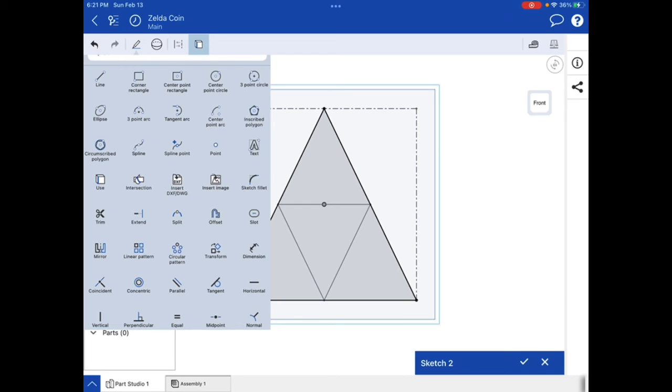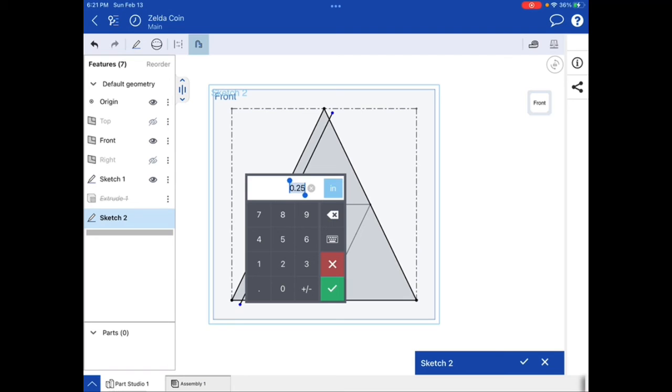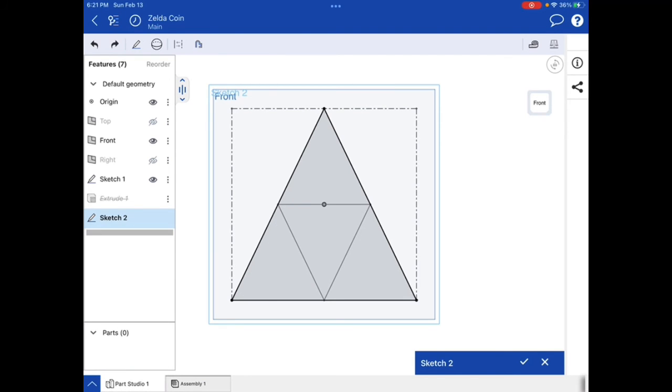We're going to go back into our sketch properties and we're going to press offset. Offset is pretty much just going to offset everything, make it nice and easy. You have to be a little careful because if you double tap real quick, it's not going to do well. We're going to reselect that tool, click the edges, uno, dos, tres, 3 sides. If you press that big arrow, you can switch between which face you want it to go. But in this case, we want it outside. So we're going to double click, and there we go.